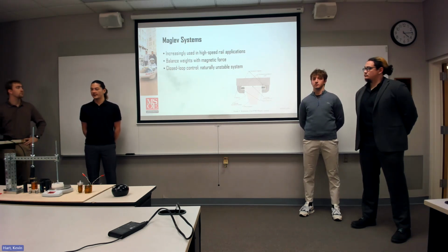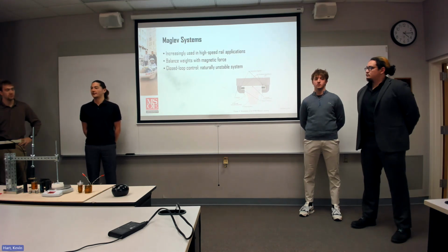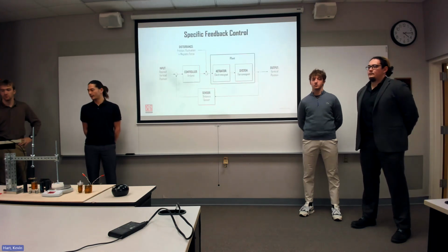And the magnetic systems require a closed loop control because these magnetic systems are naturally unstable, meaning you won't be able to find an equilibrium that satisfies your need or goal. You need to be constantly detecting the state of the system so that you can correct it.